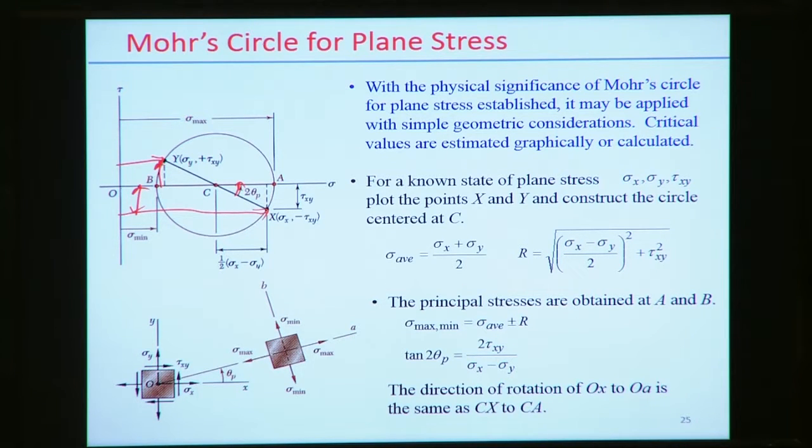So in this case, that C is basically from here to here, the center point, that actually represents the average stress value, normal stress value, and that represents the point C. Now with respect to the point C, we can define already the x and y point, and now with reference to the point C we can draw one circle.